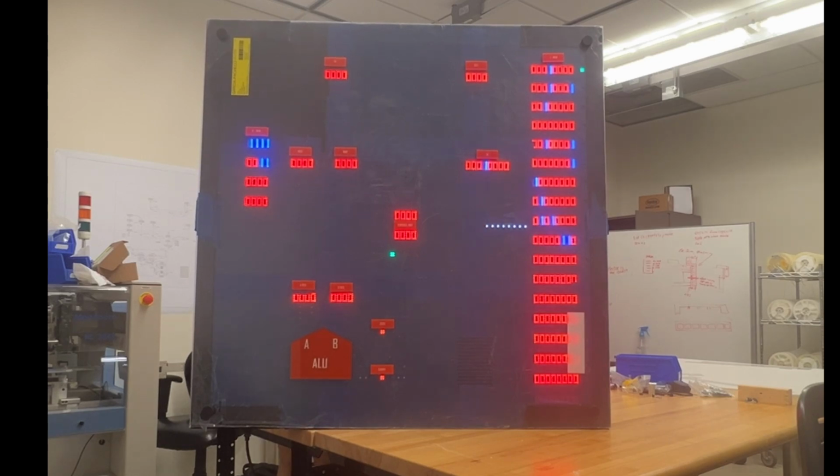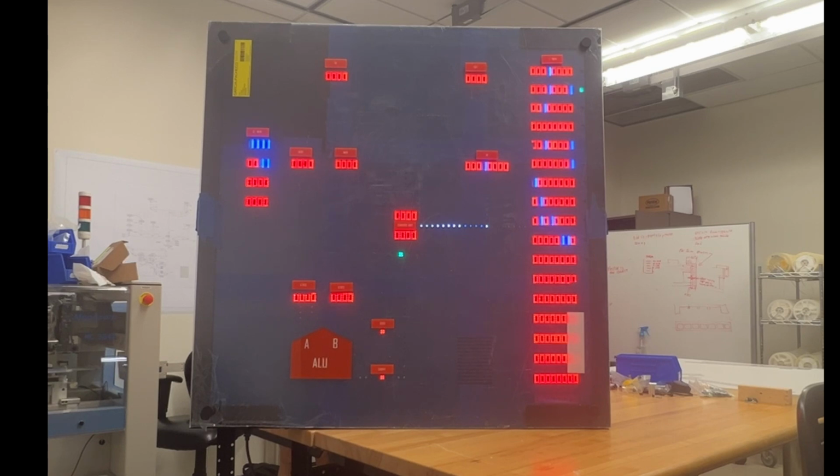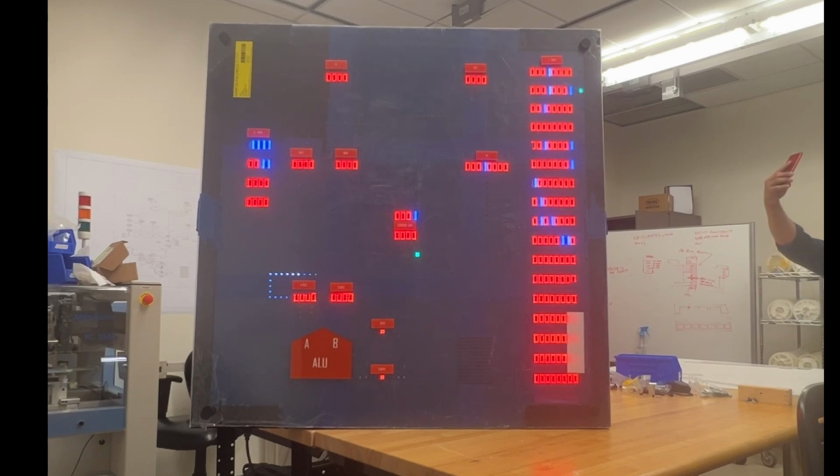The first thing the program does is clear the value of both the A and B registers. This ensures the value of the registers are not going to be modified once we begin the actual program. Afterwards, the program loads each of the registers with a specific value. The first register, the A register, is loaded with the first value in the data memory registry. This is the value of 15. Afterwards, it begins to do the same thing with the B register. The B register gets loaded with the second value held in the data memory. This value is 2.